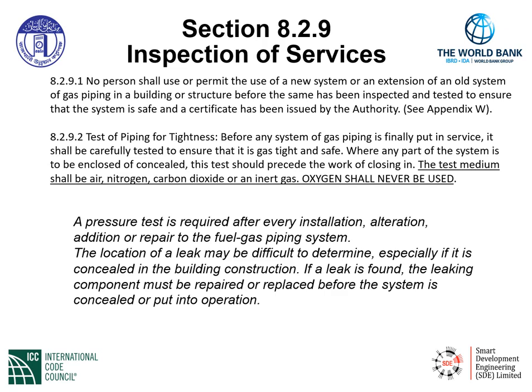8.2.9.2 gives us testing of piping for tightness. The system needs to be tested, ladies and gentlemen, so we can verify that the construction and installation of the piping system is gas tight and it will not leak. And it must be tested to be approved and prior to operation verified that it is tight.